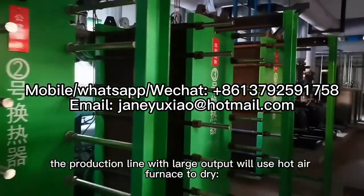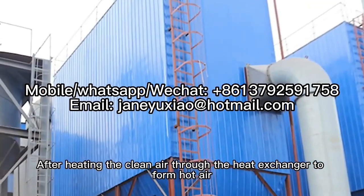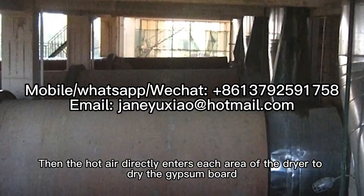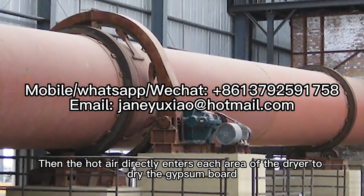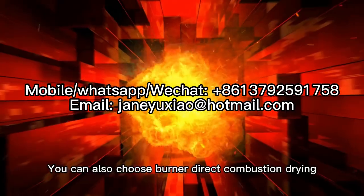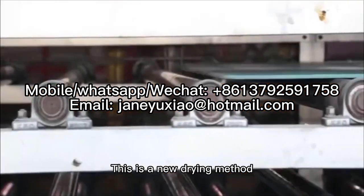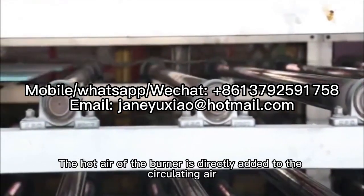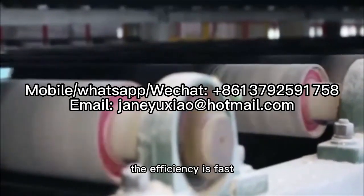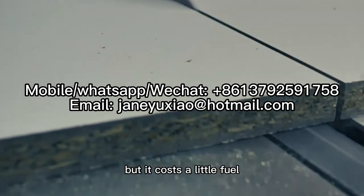At present, production lines with large output use a hot air furnace to dry. After heating clean air through the heat exchanger to form hot air, the hot air directly enters each area of the dryer to dry the gypsum board, which is clean and hygienic. You can also choose burner direct combustion drying. This is a new drying method. The hot air of the burner is directly added to the circulating air. The temperature is high, the efficiency is fast, and the product is good, but it costs a little more fuel.